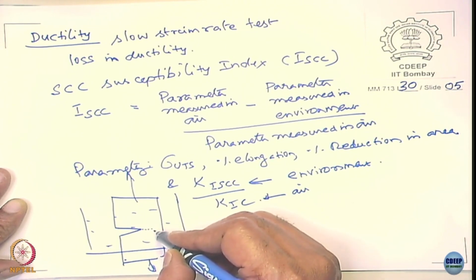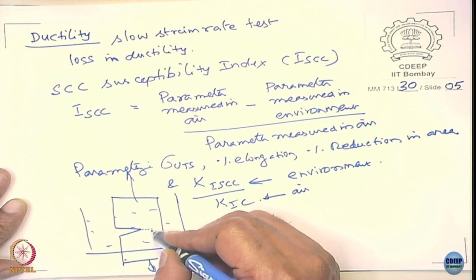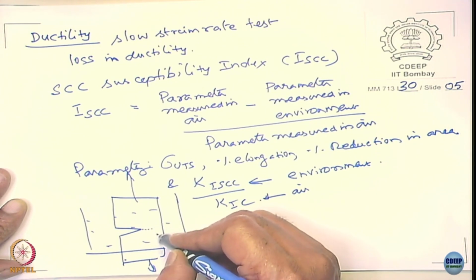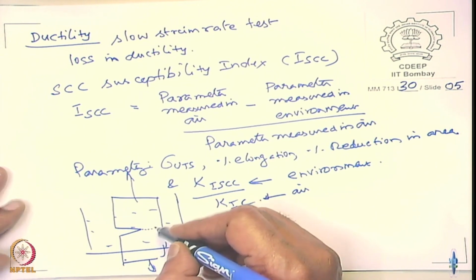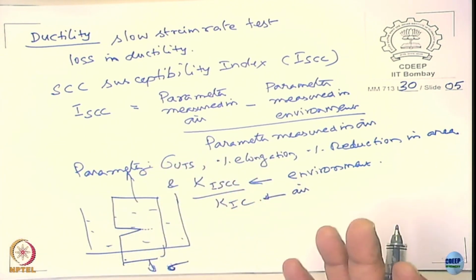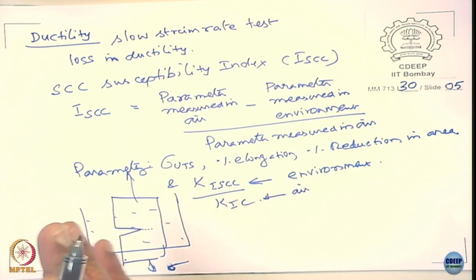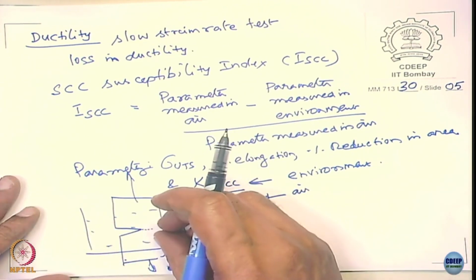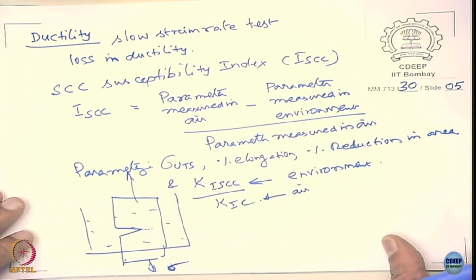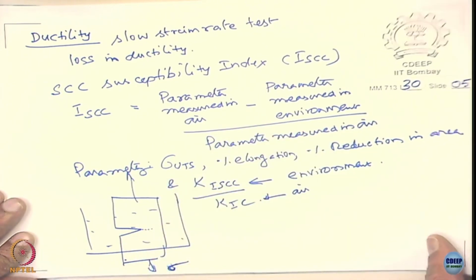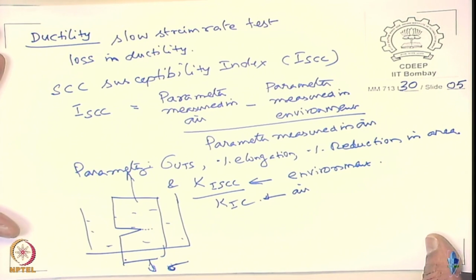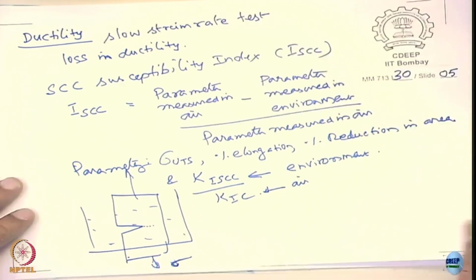The actual stress increases on the load bearing member of the specimen, and as it moves, the stress can be equal to K1C in this case. In a smooth sample it can be the UTS value, and so the metal can fail in a ductile manner. So the last ligament that fails would have a ductile component in the material, actually you can see that.